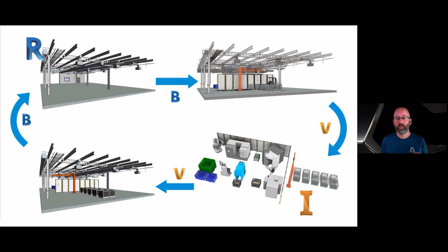We were then able to bring the Inventor model into Revit, check the design for fit and sequencing, and make any necessary changes to the building model to ensure the design is coordinated and ready to be released for construction. Finally, we saw how to update the exported Revit model from inside Inventor so we can be reassured that the coordination has been done and we can move on to the next task in our project.